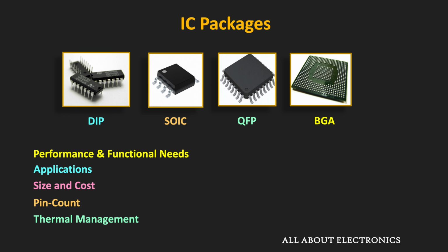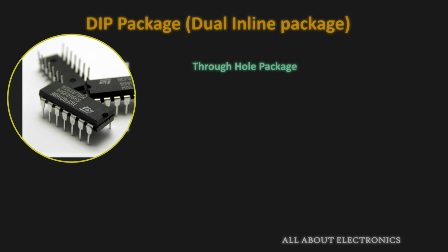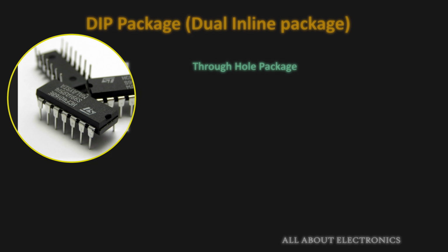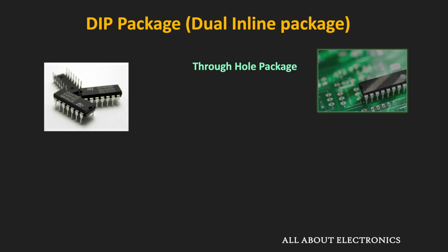So first, let us start with the DIP package. DIP means dual inline package. If you see this DIP package, it is a through-hole package. In this through-hole package, the leads extend out from the bottom of the package and they are designed to go through the holes that are drilled in the PCB.